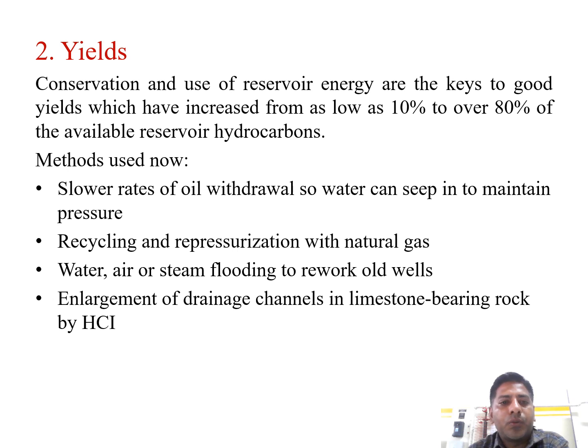Next, there are the methods available now. Slower rates of oil withdrawal, so that water can sweep in and maintain the pressures, as in the drilling process. Recycling and repressurization with natural gases, CNG or LNG, compressed natural gas or liquefied natural gas. Next, water, air and steam flooding to rework old wells. The enlargement of drainage channels in limestone-bearing rocks by acid treatment. The acid is nothing but hydrochloric acid.